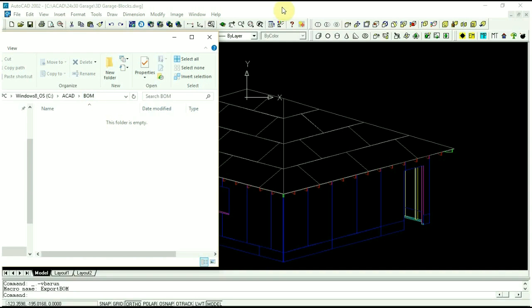And when it exports, it's going to separate the roof sheathing, the wall sheathing, and the lumber from each other. And then once it's exported to Excel, I'm going to process the bill of material and do cost estimating and cut efficiency on the lumber only. I could do it on the roof sheathing and the wall sheathing, but the programming is quite a bit more complicated on that, and I don't have those programs with me here. But I was able to write the one up for the lumber.